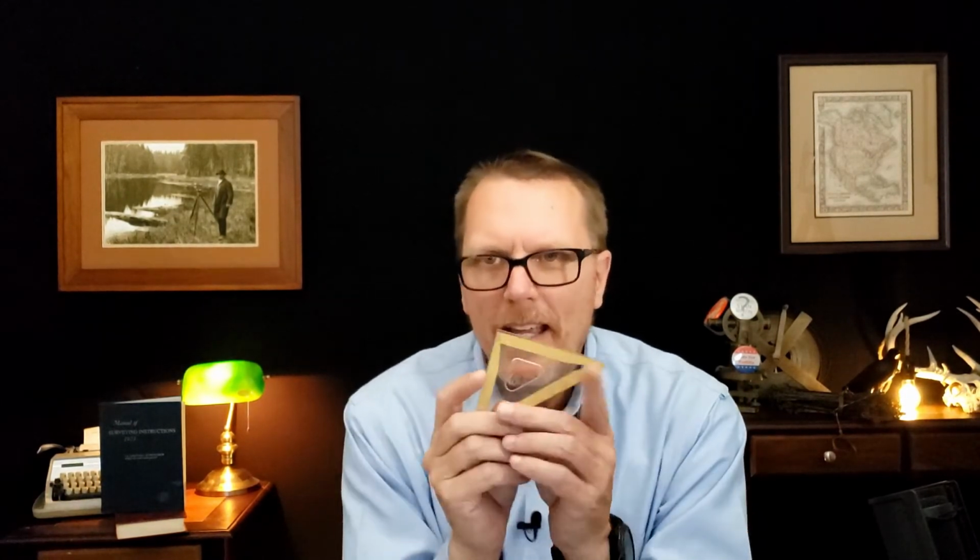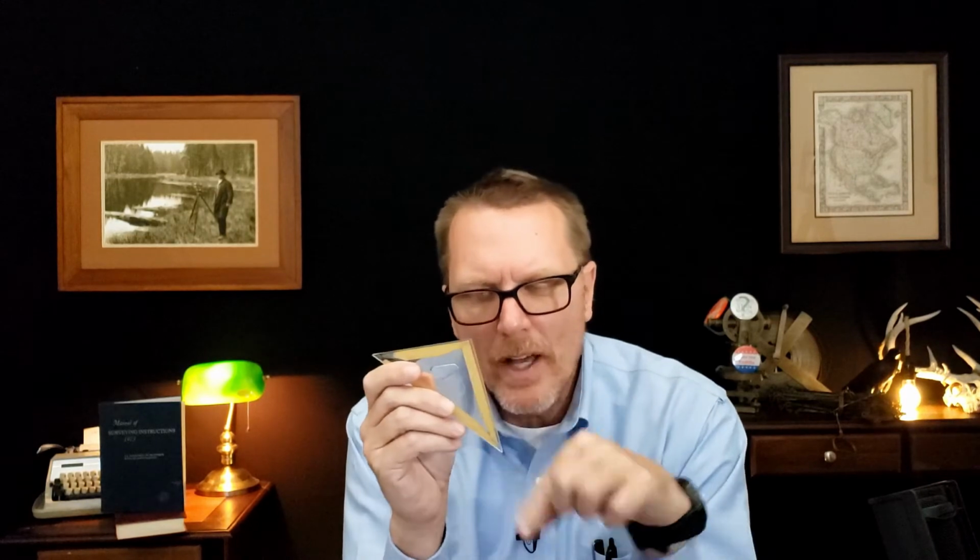But the process would be you'd take a triangle, maybe a triangle like this, and you can tell this triangle is well over 35 years old because it still has tape on it for drafting on Mylar, so you didn't smear the ink. Another story for another day. Anyway, you would lay it in the grid, and you would draw these straight lines, and you would grid the paper out, grid the plans out, and then you would take a scale, something like this, and you would scale down your northings, and then you would have similar grid ticks.